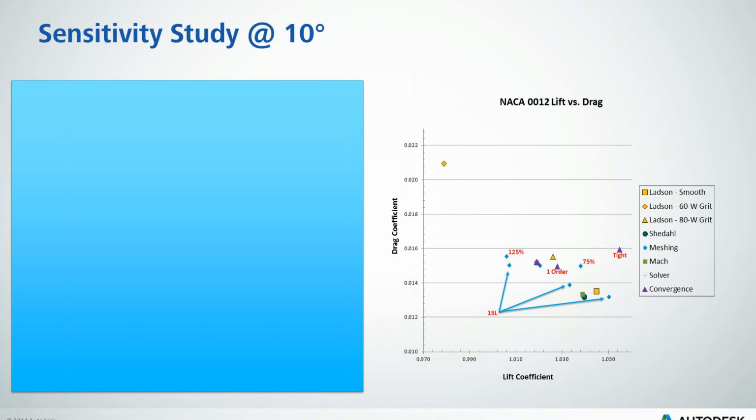So what we did is you can turn off the range slider with the auto convergence, and I'll show this in a moment, and you can start adding manual extra orders of magnitude to the different convergence terms. So what happens here is I add an extra order to those terms, and then an extra 2 orders and an extra 3 orders.